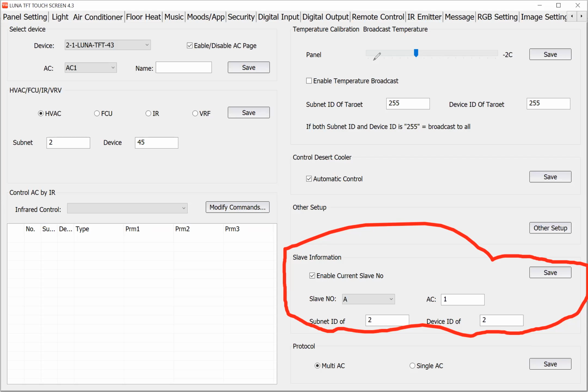Mr. Arif, absolutely, if you have a damper, they work. If the average of the room is very different from the room temperature that you chose, the fan works on the highest speed, and all of your dampers are open.